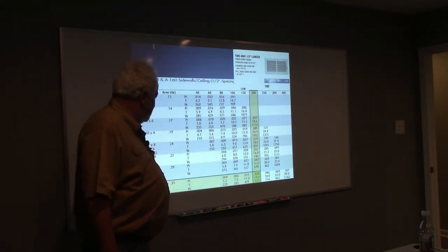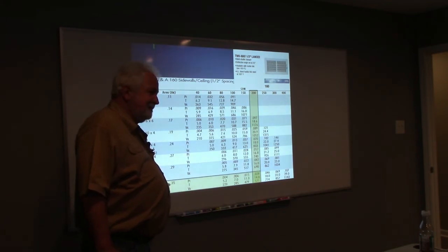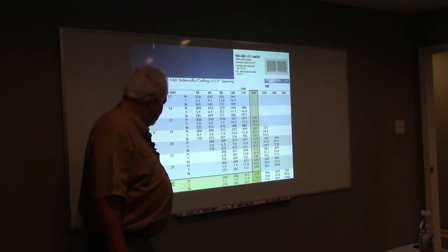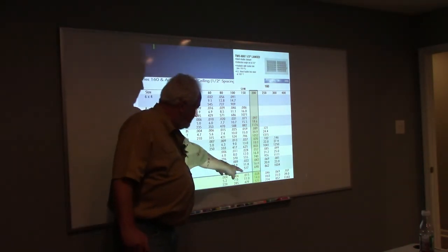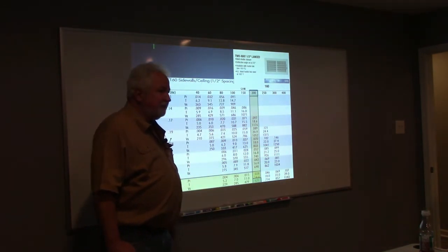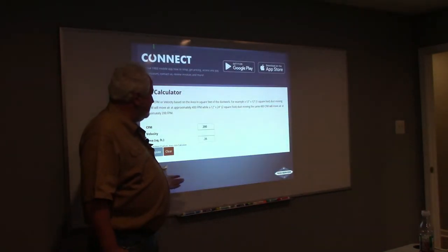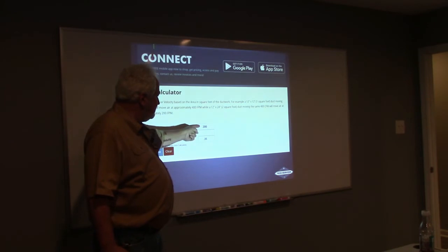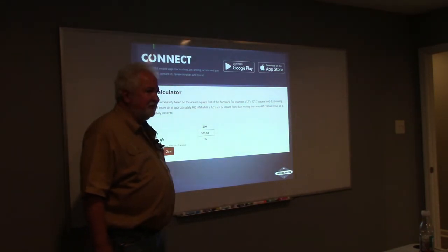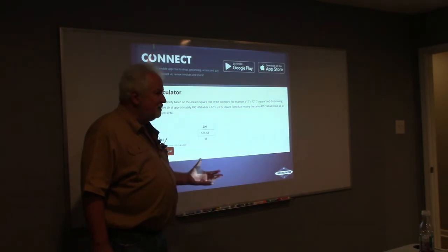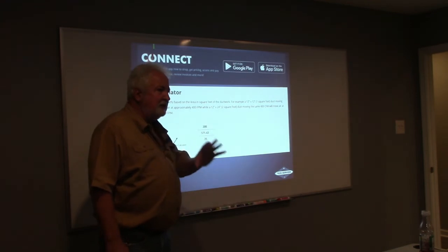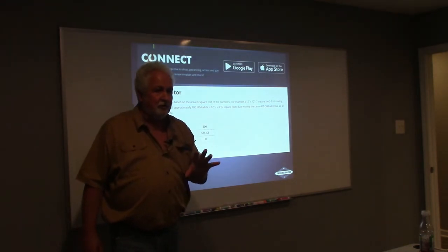There's a difference in the free area. Wow. Watch what happens. 0.35, 571 speed, 200 CFM. Plug it right back in here. 200 CFM, 0.35, 571. It's screaming at you, this math works. The calculators work and they can work for you.